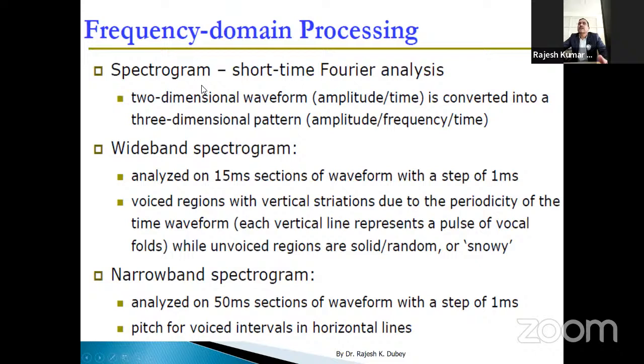Next is the spectrogram, which is short time Fourier analysis. We know Fourier analysis, but here we use short time Fourier analysis. That is, we do not use the entire signal, only a short duration, and we call it short time Fourier analysis. In that case we see what frequency content is there at what time, and what magnitude. That means it is a representation of magnitude, time, as well as frequency. That's why it is named spectrogram. We can use a wide band spectrogram or a narrow band spectrogram.